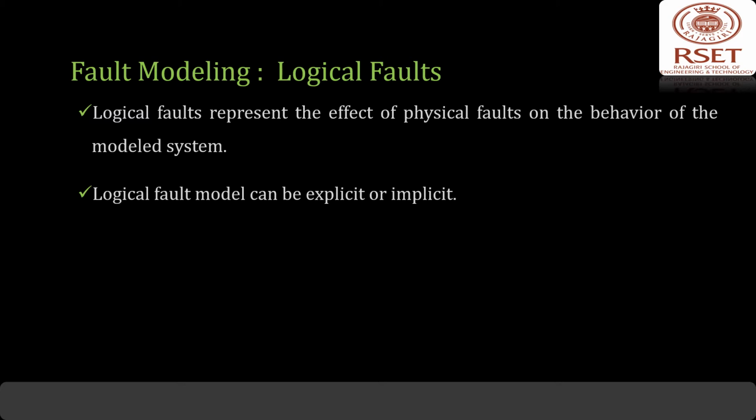An explicit fault model defines a fault universe in which every fault is individually identified, and hence the faults to be analyzed can be explicitly enumerated. Whereas an implicit fault model defines a fault universe by identifying the faults which are of interest, or on demand, typically by defining their characterizing properties.